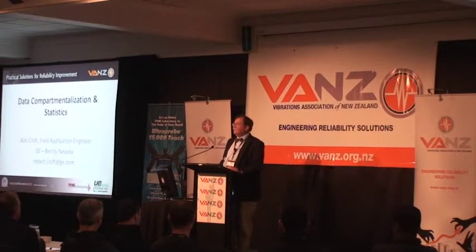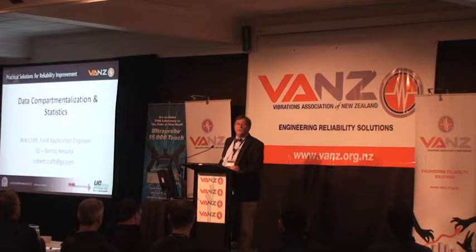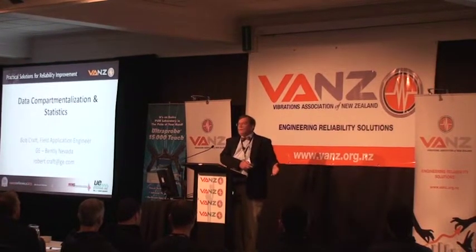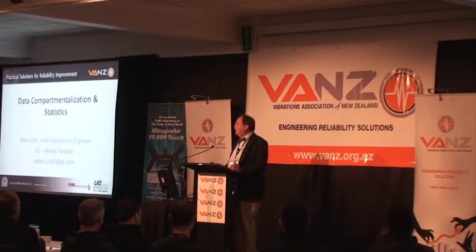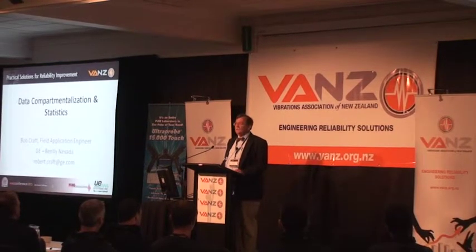Because we often run into a situation, especially on variable speed, variable load types of machinery, where the data may not be comparable from the last time I took it to how I took it today, just based on the way the machine is running, or the operational demands, the speed, the temperature, the pressure, the load that we're putting on these machines to satisfy our company's productivity and operational requirements.